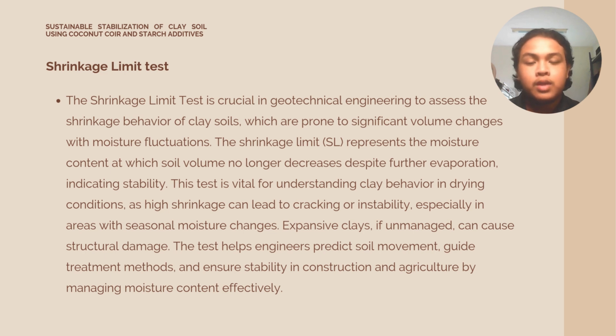Next is the shrinkage limit test. The shrinkage limit test is crucial in geotechnical engineering to assess the shrinkage behavior of clay soil, which is prone to significant volume change with moisture fluctuation. The shrinkage limit represents the moisture content at which soil volume no longer decreases despite further evaporation, indicating stability. This test is vital for understanding clay behavior in drying conditions, as high shrinkage can lead to cracking or instability,